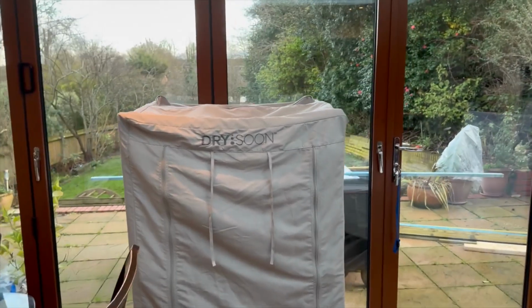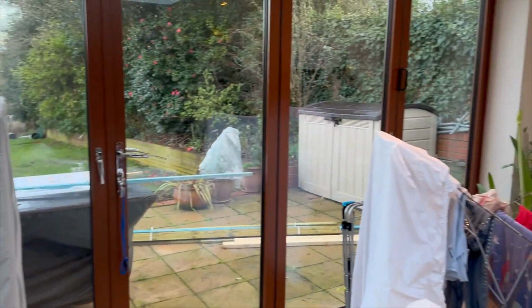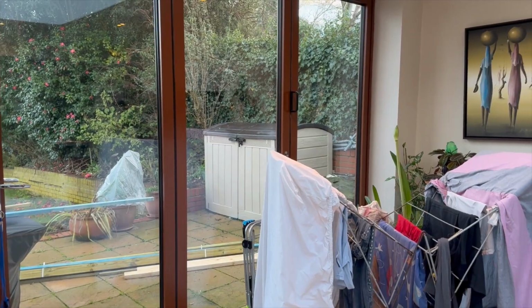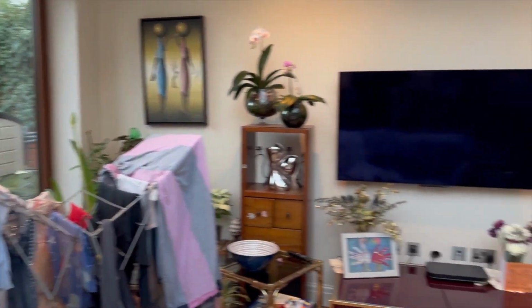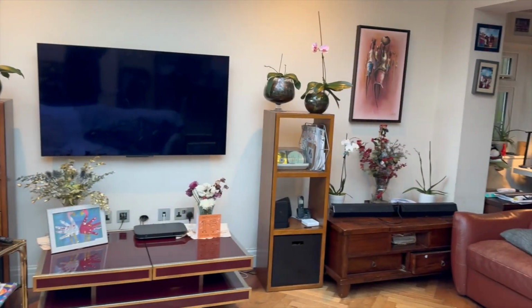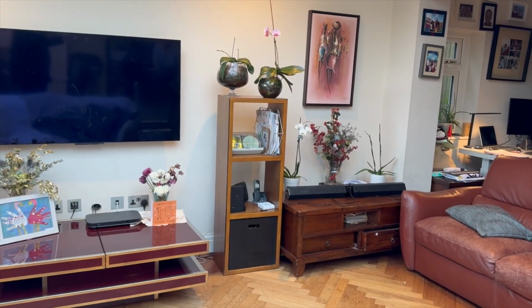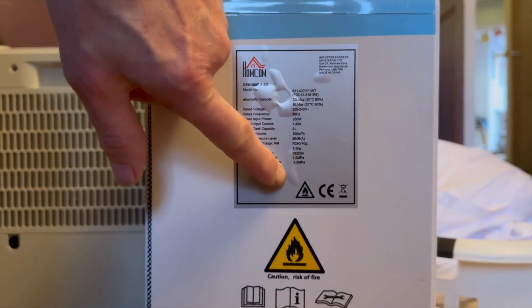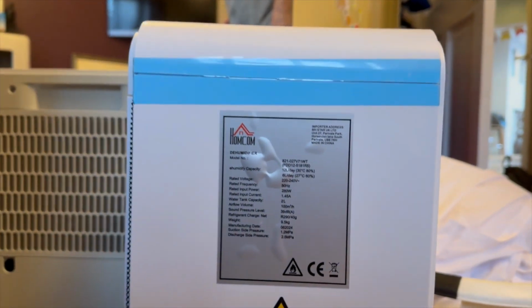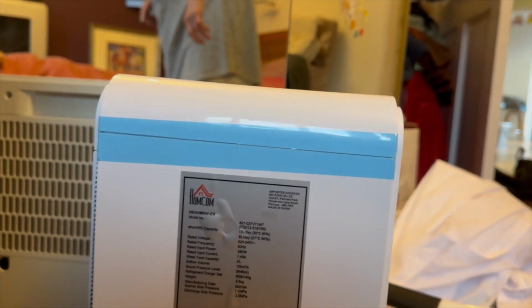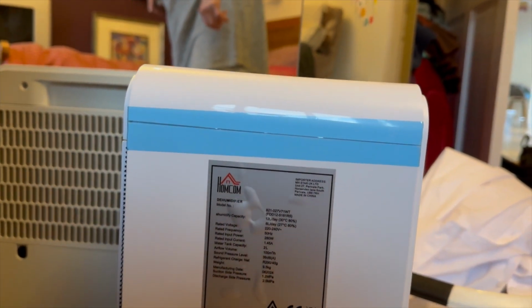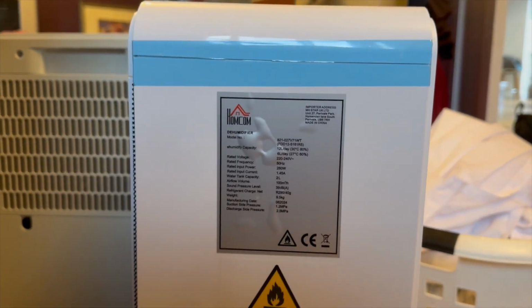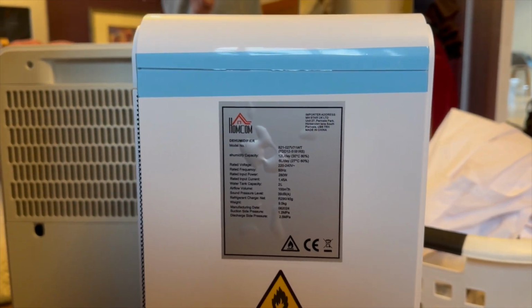Drying clothes enclosed internally, particularly with a heated dryer, needs to be compensated for with a dehumidifier, and your mother-in-law has a dehumidifier, but it's not strong enough. I'll have a look at that. It says it's 12 litres per day, but it should be 20 litres a day to cope with the amount of vapour that's generated. I would say you're going to have at least one, if not two, dehumidifiers to cope with the amount of vapour that's been generated here.